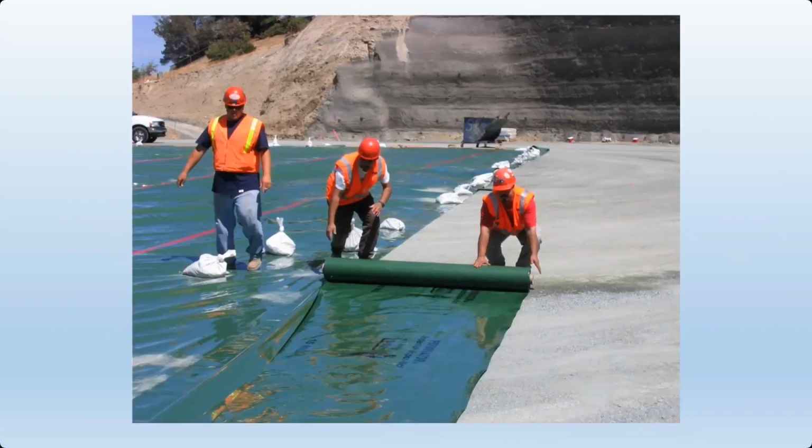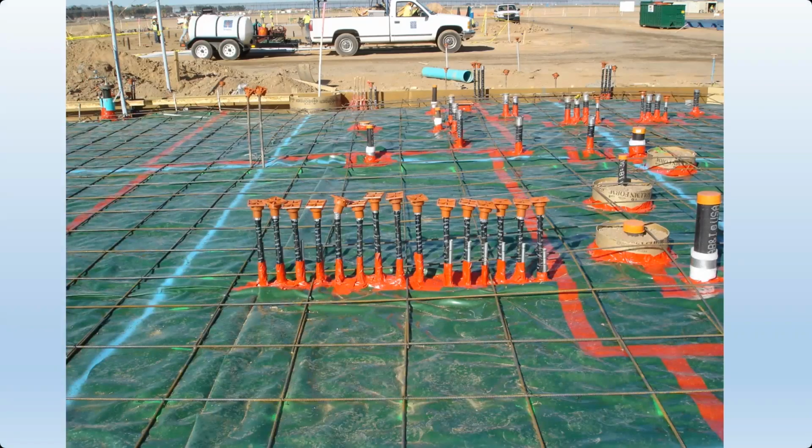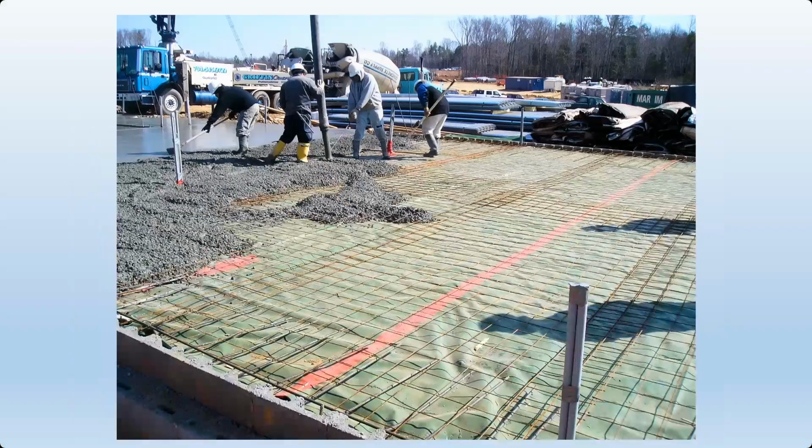So here are just some quick snapshots of these systems going down, and pay particular attention to the penetrations. Yes, these systems can also be used in conjunction with an active radon mitigation system, i.e. a 24-hour day running fan system to create a negative pressure underneath the slab. But these systems are most commonly made of virgin resins as opposed to reclaimed, recycled, which the virgin resins are going to be much more durable for withstanding the rigors of concrete placement and the trades on top of them.